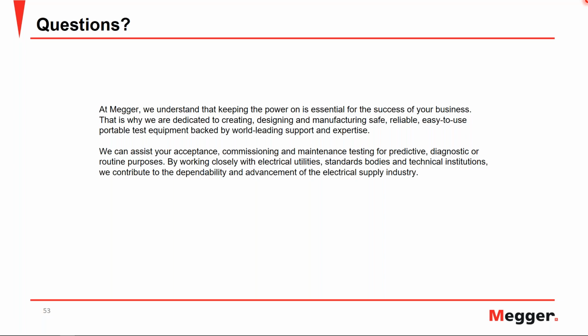There are alternate ways to perform power factor testing, in the sense that you can vary the voltage and see how the insulation reacts to the change in voltage, which we typically call the tip-up test. Charles also talked about frequency-based power factor testing, where you vary the frequency and perform the power factor testing to analyze the results in a better way.